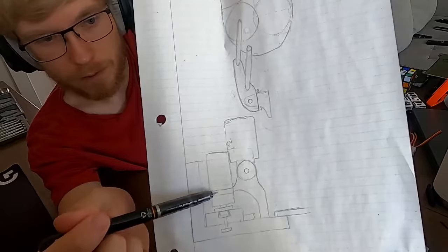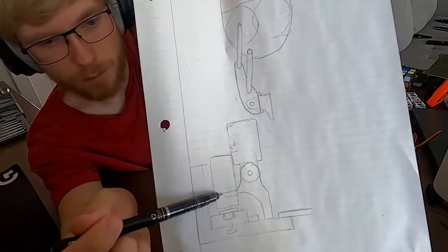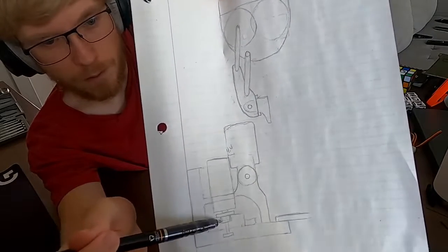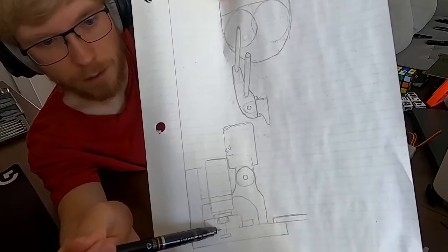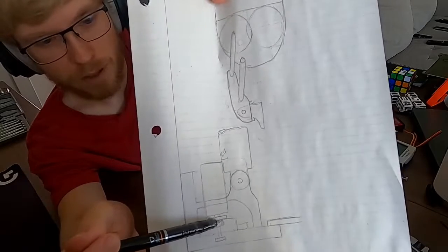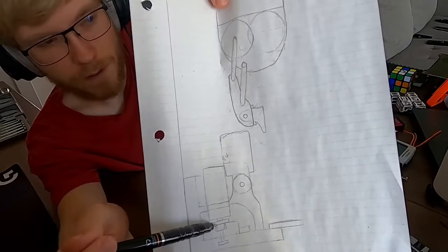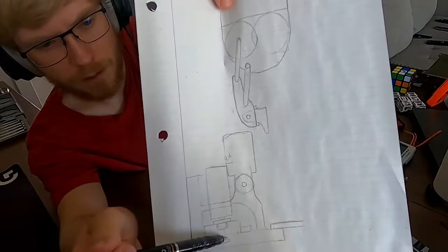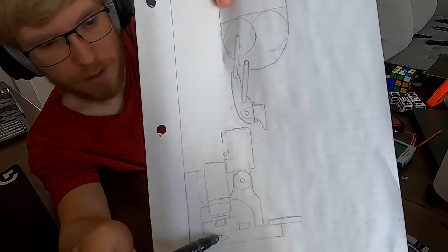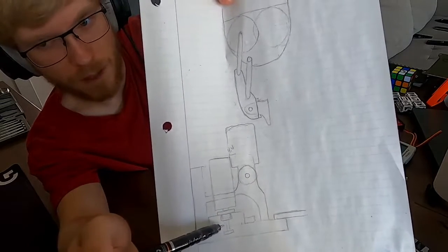Bottom, this will be the flat pivot face that goes up against the first servo. Then there'll be an arm that stretches out, which this servo is bolted into. So there'll be some bolts right around there, which will hold the servo in place. This bottom gear is then nice and thick, so I can do little countersunk, separate assembly kind of bearing almost. So that will bear the force of this, and I'll square out the bottom of it so it locks into this bottom base and doesn't actually rotate at all, so that the bolt doesn't slowly loosen with time.